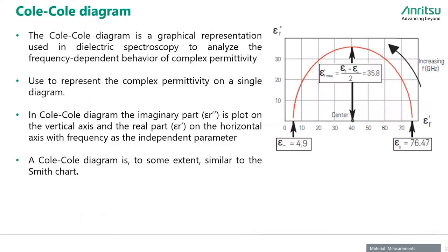Then we also do the measurement of the Cole-Cole diagram. You might have heard about it. The Cole-Cole diagram is basically a graphical representation used in dielectric spectroscopy to analyze the frequency-dependent behavior of a complex parameter. In this particular graph, what we do is plot the complex permittivity on a single diagram